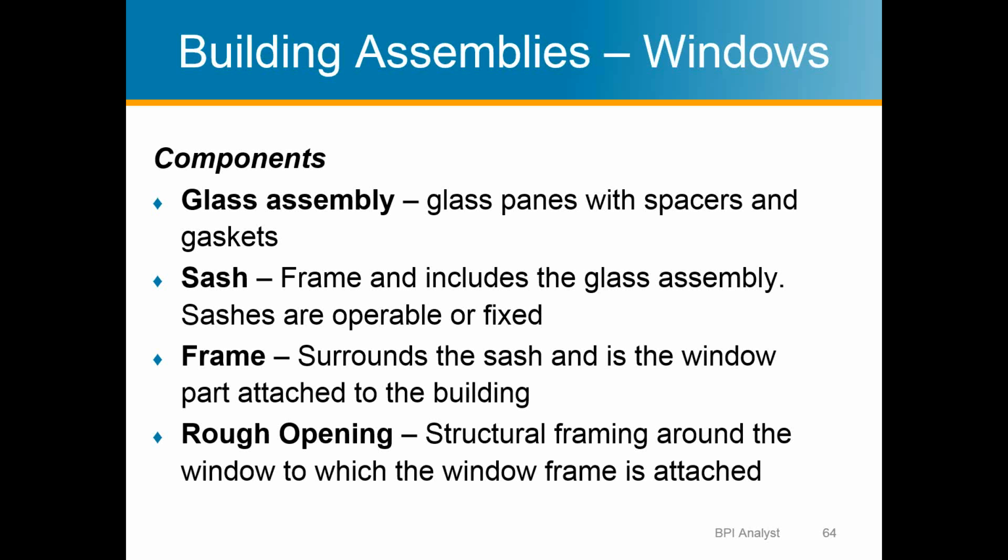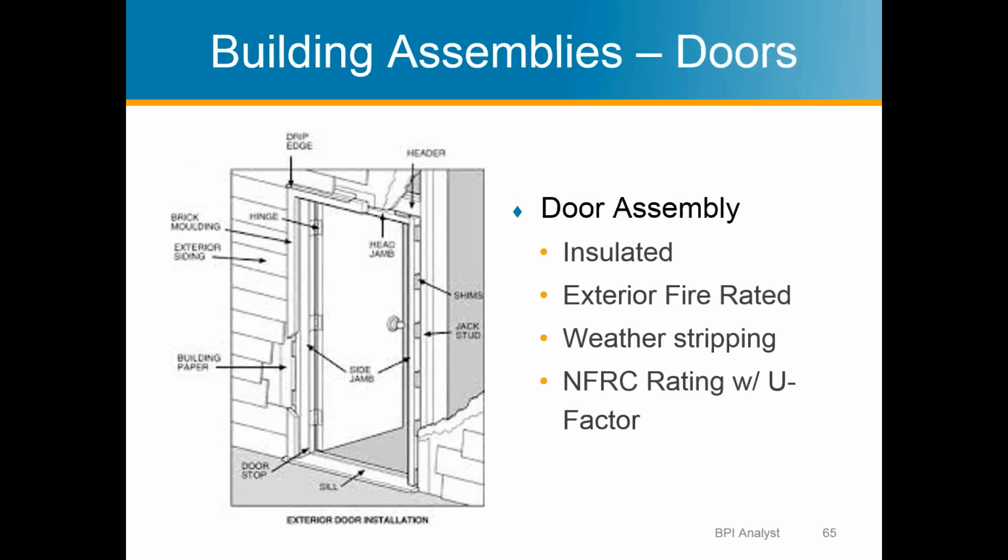If you're in the field measuring it, you need to take into account that the drywall is there. So if half-inch drywall, your opening is going to be at least an inch in each direction larger. But that's the rough opening. That's the where's the wood? What's the size of the wood in that wall for your window?